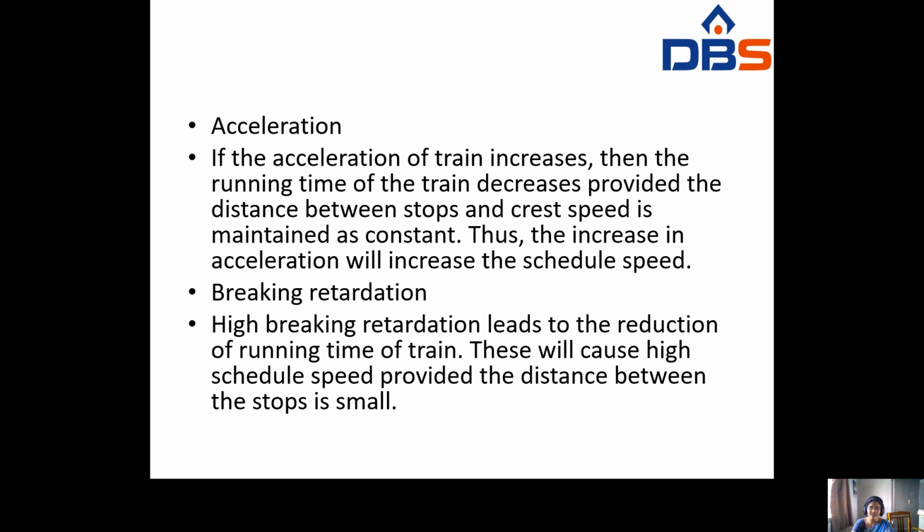Now acceleration. If the acceleration of the train increases, then the running time of the train decreases, provided the distance between the stops and the crest speed are maintained constant. Whenever acceleration increases, the running time of the train decreases.